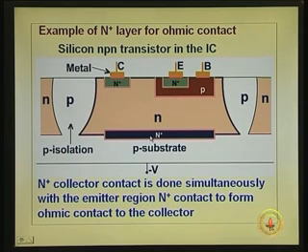So, we put that selectively. In fact, you can do that by oxidizing and diffusing only in this portion. Then grow an epitaxial n type layer on top of that. P type layer, n plus layer in selected portions, then the n layer, maybe 10 microns, 15 microns, depending upon the integrated circuit technology that you have got. Today, they talk of 1 or 2 microns, this whole layer.